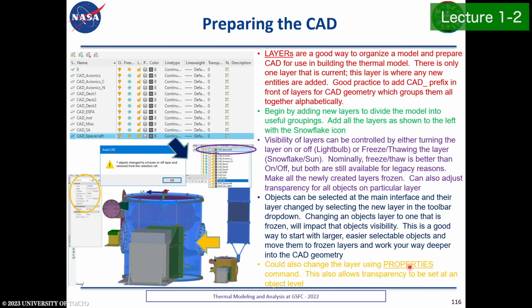Very often, if I bring in a step file, it's going to be one block. A block in AutoCAD is, everything is contained in this one object. You select the whole thing. So you need to explode or burst that block down to its constituents. So I burst it, it's going to burst it down to the next level of assemblies. So you have to keep bursting and bursting until all you have left are non-blocks. Because now you've taken all of the assemblies and turned them into 3D solids.